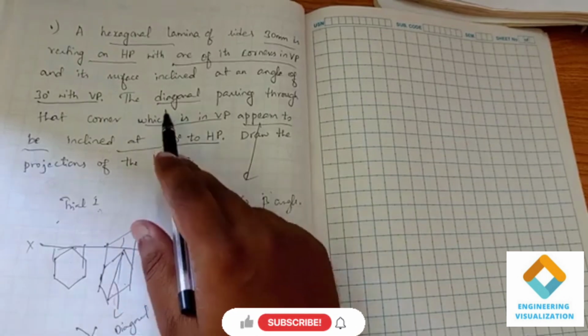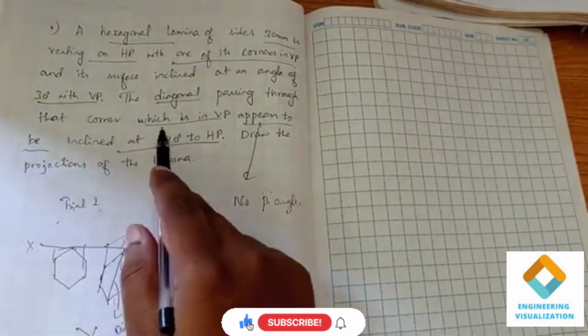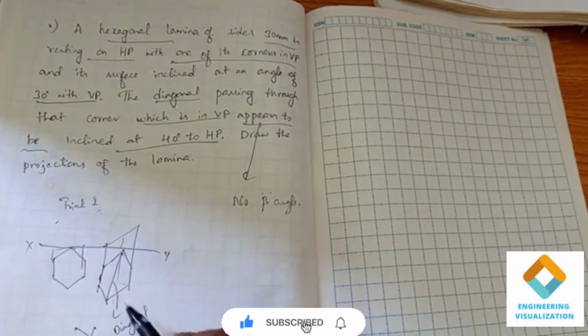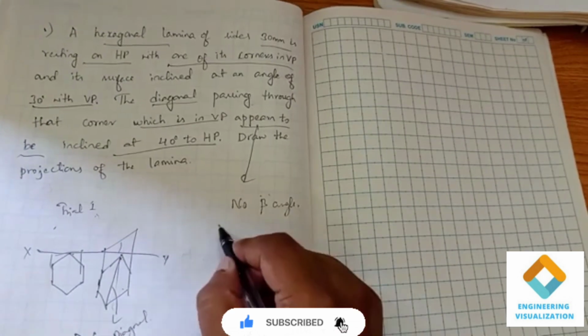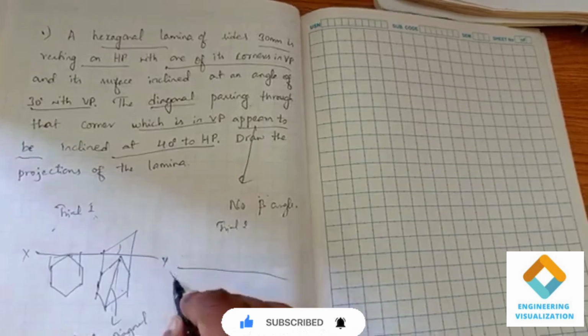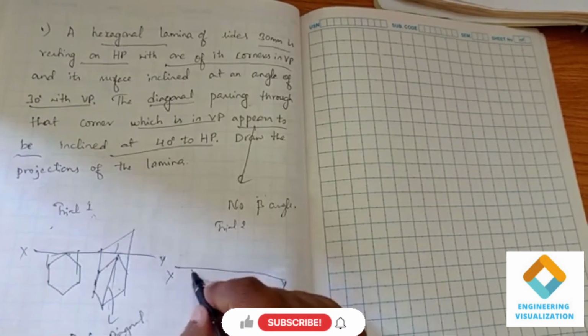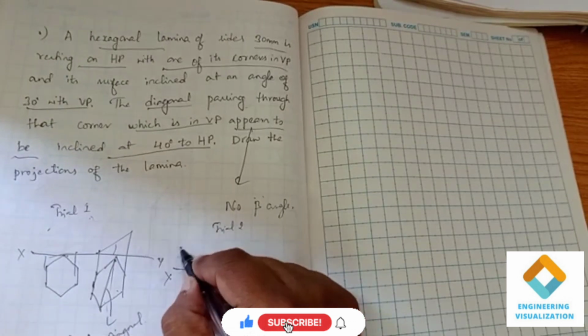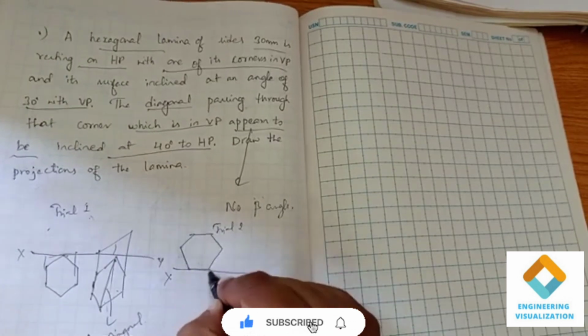Now with the second condition, the diagonal passing through that corner which is in VP, this diagonal is not there in the VP, it is there in the HP. So that's why this trial is wrong. Now we see trial 2. In this trial 2 we are going to construct like this, an edge touching the HP plane, corner in the VP plane, the first position.